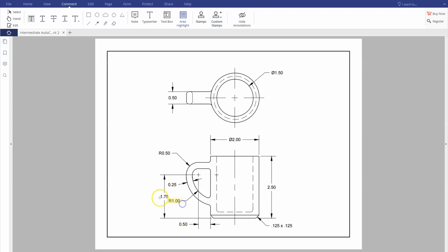You can see that this one has a radius of 1. One of the rules you need to remember is that these arrows, especially in AutoCAD and all of your other drafting programs, always point back to where the center is. So if you're looking for the center of this one, if you follow this arrow, it will point back to this little plus here. So when I go to create this radius on the outside, I need to reference that center. Everything else on here should be straightforward on how you create everything else.